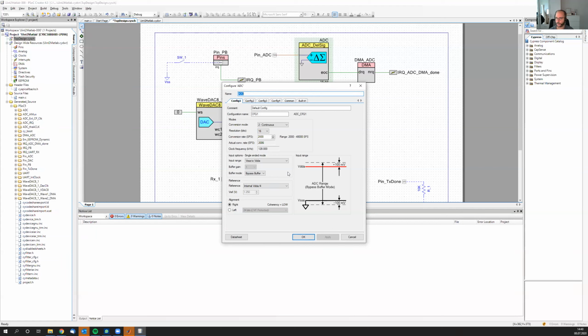Now, basically, you have two possibilities on how to do that. It's a rather proportional or very linear calculation. You simply take that value and you multiply it by 5 volt plus 200 millivolts divided by 2 to the power of 16 kind of thing, yeah? You can do that in MATLAB. So this would be one approach. You transmit the raw data from the ADC as it comes out of the ADC, transfer it to MATLAB, and in MATLAB, you do the calculation manually to volts, okay?